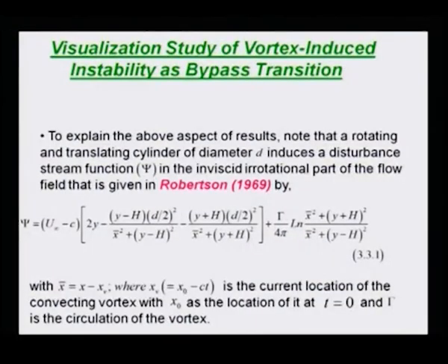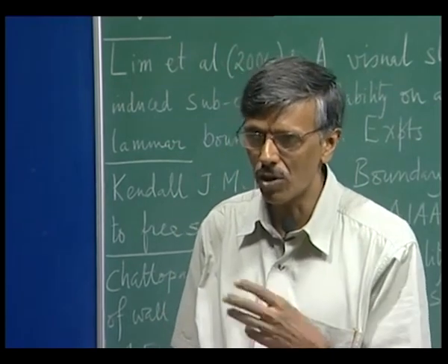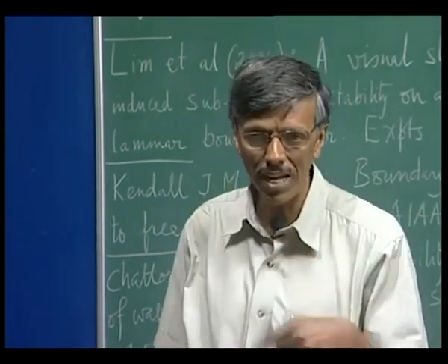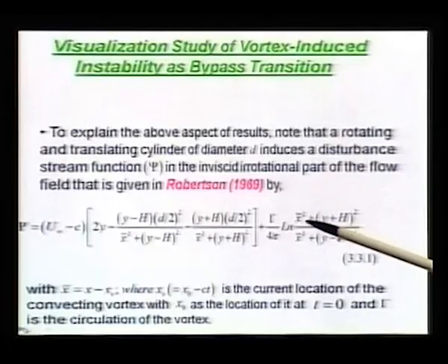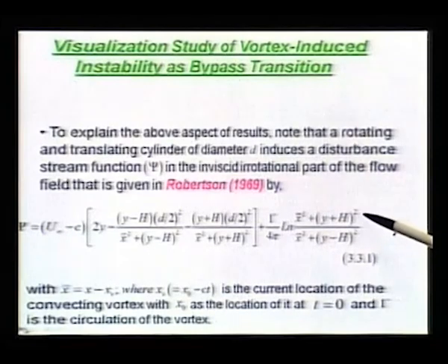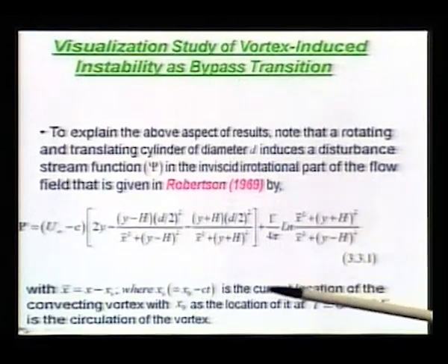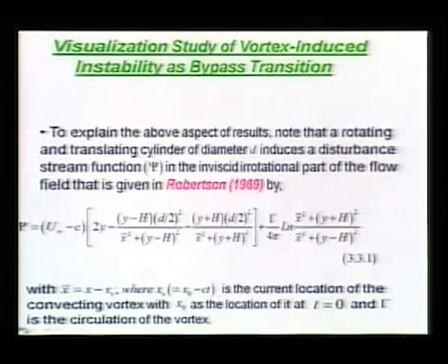Well, it's a subtle thing, because we are creating a relative speed, and that relative speed, if you recall, would create, as the cylinder is rotating, the circulation. So, gamma itself that we have here is a function of C. That is why, and the dependence on h is pretty much obvious. And of course, you can also say that C comes in through the definition of x bar, because that is what you have there.